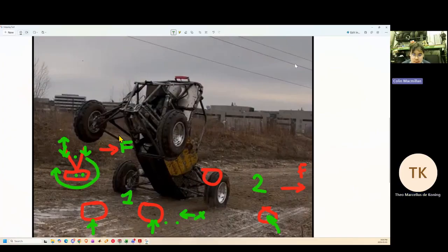It's definitely a more complicated load situation. It might be useful to get it through a data acquisition system. The thing is, with a DAQ, if we have strain gauges on the control arms and on the clevises, that information is useful, but you have to be able to build a calculator to interpret those numbers and give you useful information, which then becomes hard. What's hard about the calculator?